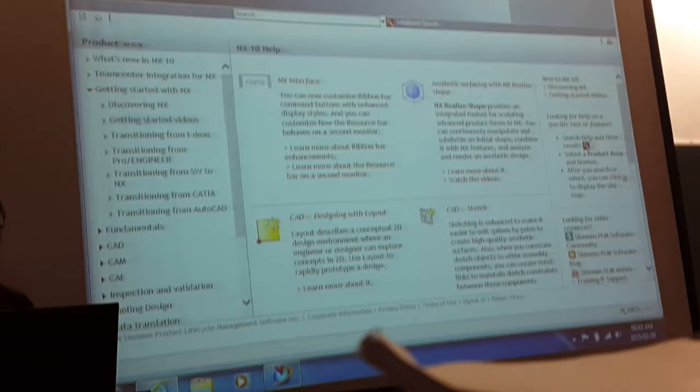and we go into sketch mode. We use the profile feature to create some arbitrary profile that we will use. So basically what I'm making is a little plate, perhaps a thick plate with some holes, for example. Alright, so the profile option allows you to draw straight lines as well as arcs. Starting off with the straight line option, so I'm literally going to go across from there to there, and then maybe there to there, there to there, and then I'll swap over to an arc.